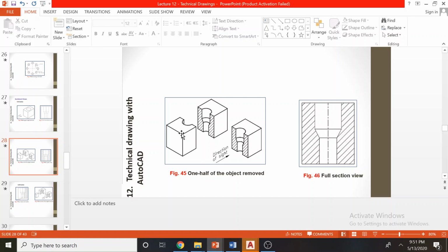When you cut from the middle and remove this area, and look at this directly, you can clearly see this shape, as well as have an idea whether this is a round shape or a square shape. So why do we hatch this now? This is called hatching. Whatever we can see clearly, we are going to hatch. If you don't hatch the other area, that means this hatched area and this unhatched area are not aligned. So this area should be behind the hatched area.